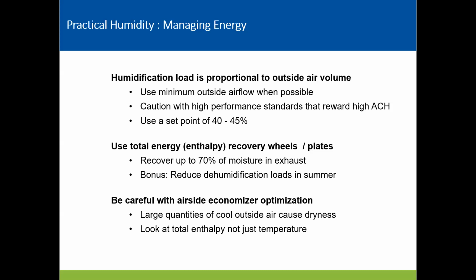Total energy or enthalpy recovery devices are also very useful. In addition to recovering heat from the building, they're also recovering the water back into it as well. I've seen some studies that show that they can recover as much as 70% of the moisture. So that has a great reduction in the amount of humidity energy that needs to be added, and in some climates can even reduce dehumidification loads as well.